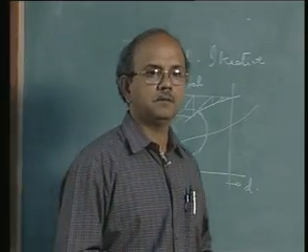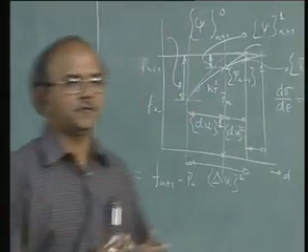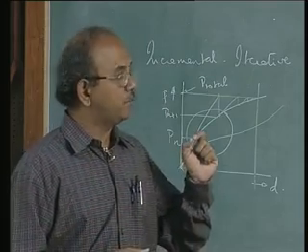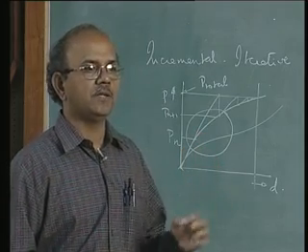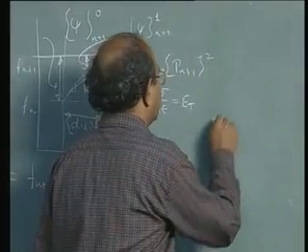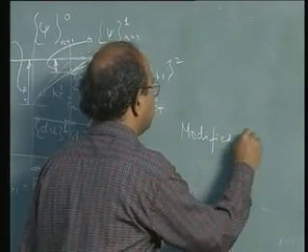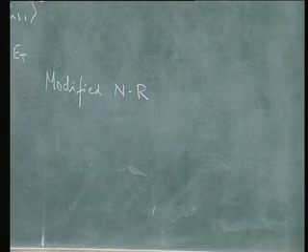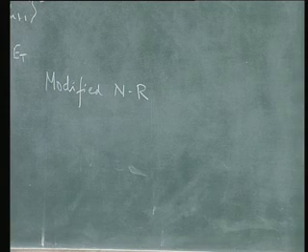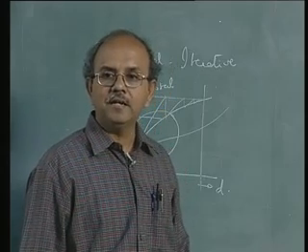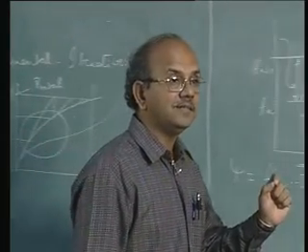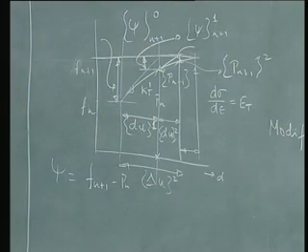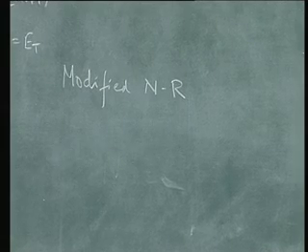So, clear? Any questions? What is the difference between full Newton-Raphson method and...? Yeah, I am coming to that. Is there any other method for Newton-Raphson? There is. Since I made a statement about the full Newton-Raphson method, there is also a method called the modified Newton-Raphson method. So what is the modified Newton-Raphson method? Here you do not calculate the stiffness for every iteration.